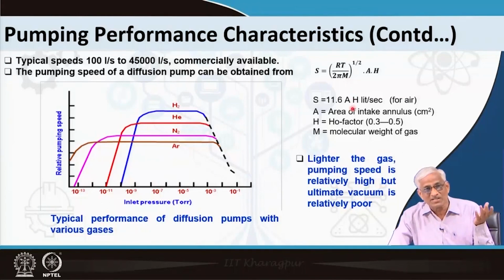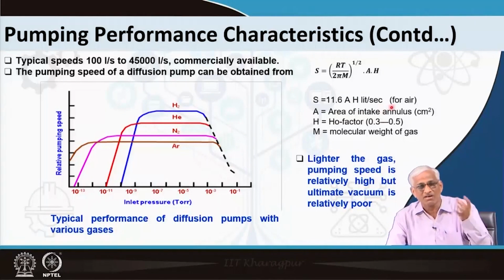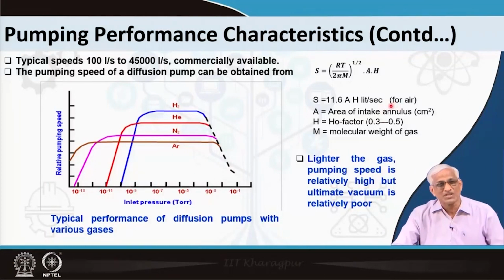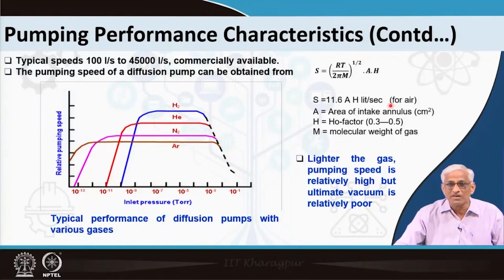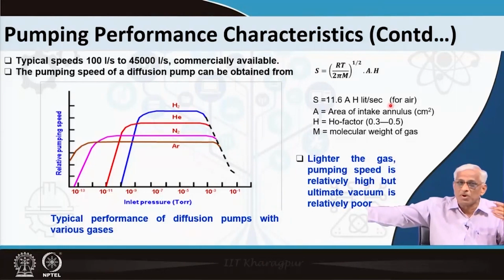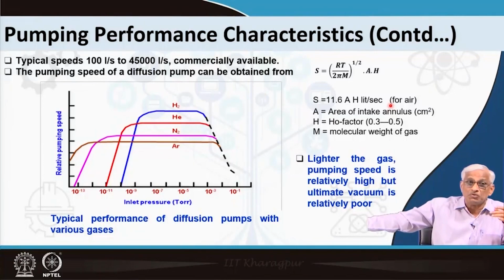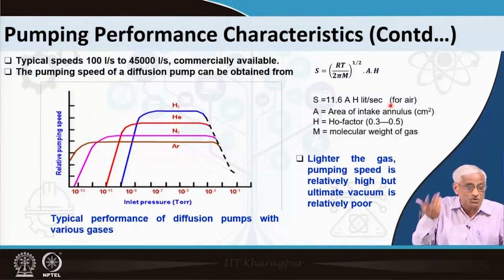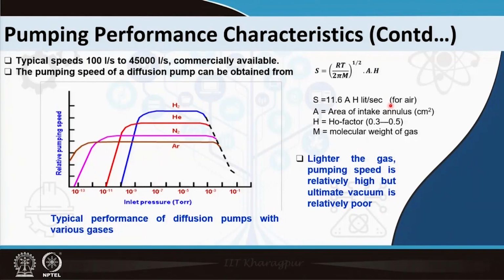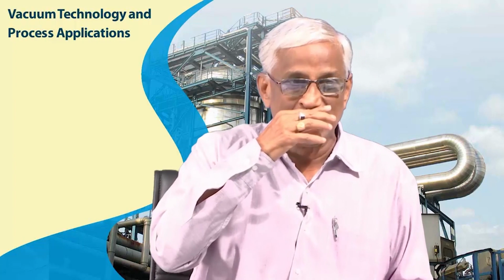Okay. It is not like the viscous rho v d by mu and all these viscous drags, where if you drag some molecule, it will drag. All those concepts cannot be applied once you cross 10 power minus 2 torr. Molecules are travelling on their own. It does not know that there is a pump from the chamber that is creating good vacuum, or that it should go there. Nobody knows. It so happens that it will go in all directions, but whatever goes in this direction is caught by the oil molecule. So, the return journey is not there, but the forward journey is not accelerated. In viscous flow in the rotary pumps, when you try to suck, that is why it is called suction, but on the high vacuum side it is only pumping, molecular pumping.